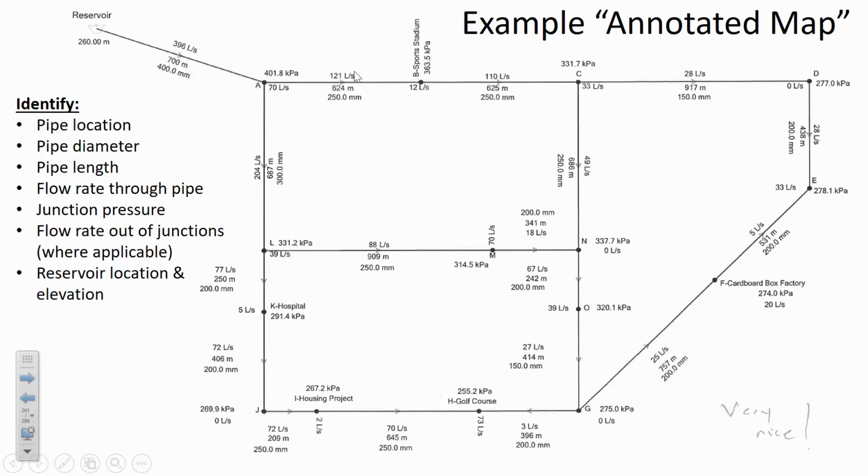The vertical offsets that you can program when you're setting up the annotations will put it above the line or below the line, and so this person did a good job setting it up so that it was really clear and none of the information was on top. Sometimes you'll have to manually drag the labels to the side, but that's not too hard.